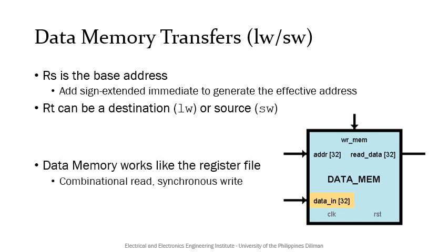We will assume that the data memory simply acts like a register file with combinational reads and sequential writes. More details on how real memories work will be discussed in the last 2 weeks of this course. To store or write into the data memory, both address and data must be provided, and the write mem signal must be asserted when the clock rising edge occurs. Note that even when the intention is to write, the data mem may still try to fetch its value and output some data at the read data port.